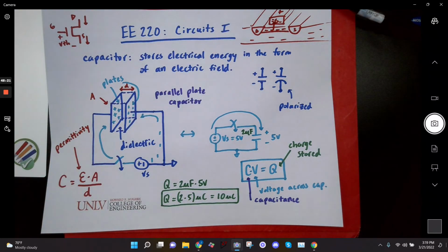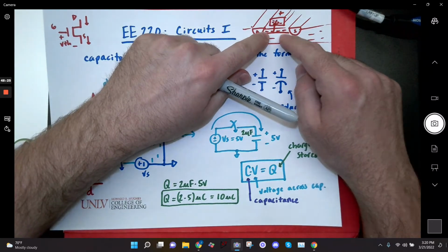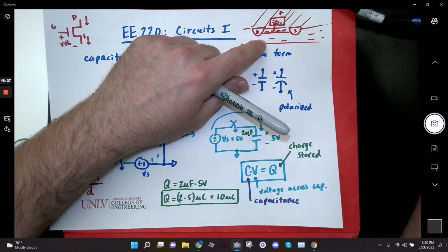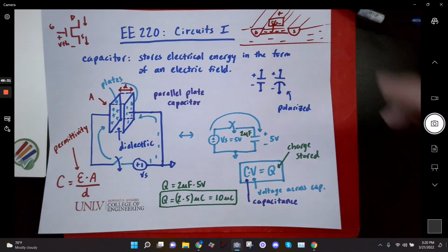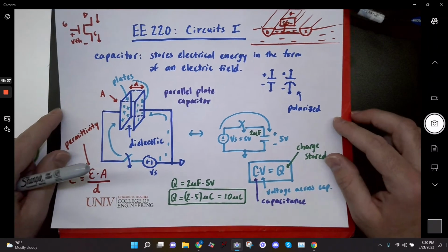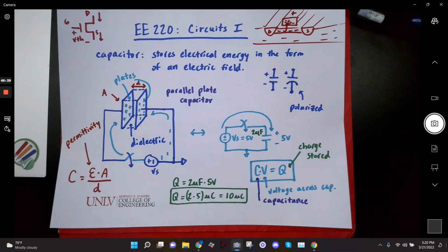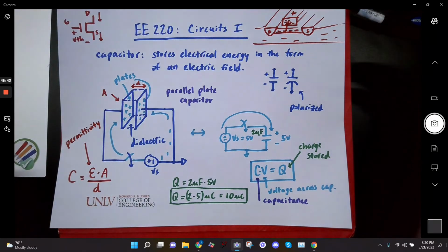They're the same charge. And now, since there's electrons sitting on this gate that will repel other electrons, the threshold voltage is larger. And so they actually manipulate the threshold voltages of these devices. And a higher threshold voltage would be a 1, and a lower threshold voltage would be a 0. And so that's how flash memory works. That's why it's non-volatile. And you don't need power to keep it, because it's actually physically manipulating the structure of the devices. It's not just stored charge.